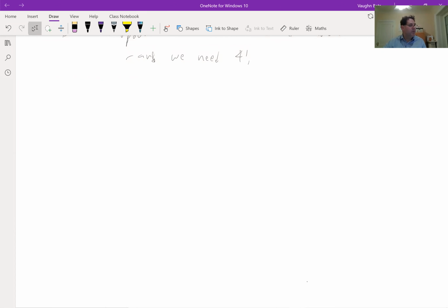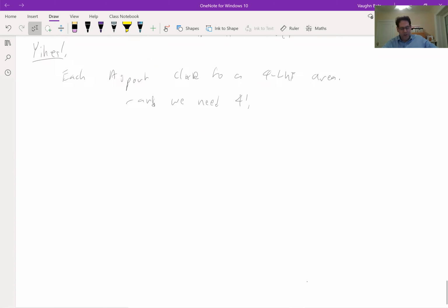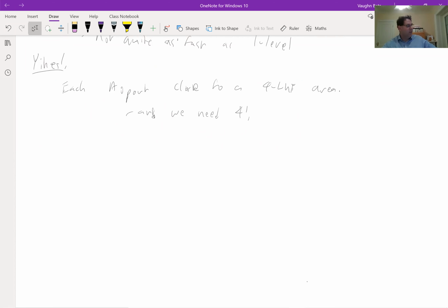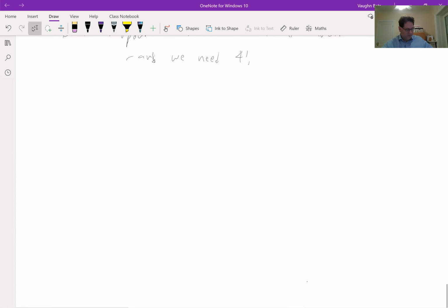So it means you can't neglect routing area. There are some FPGA studies that have said, well, we're just going to count how many logic elements we used, and we'll come up with a new logic element, and maybe we'll multiply by the area per logic element. But we're not going to worry about the routing because it's kind of hard to estimate. And you can't do that because the routing is commonly bigger than the actual logic elements. So you can't ignore it.